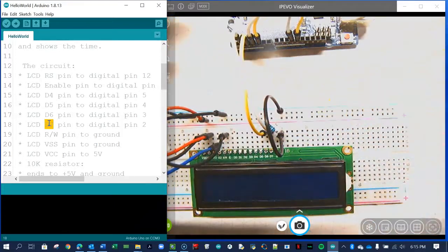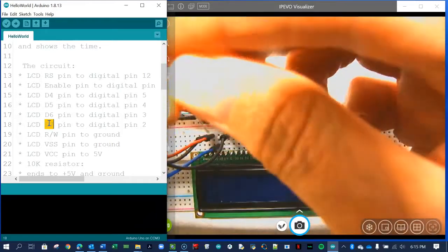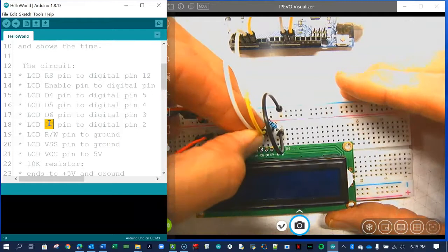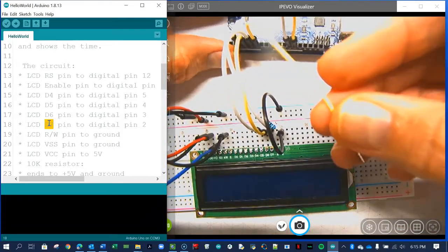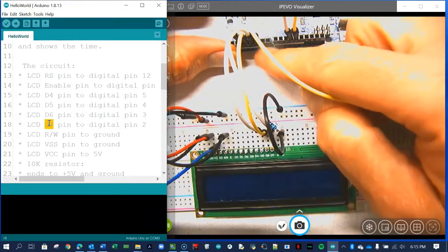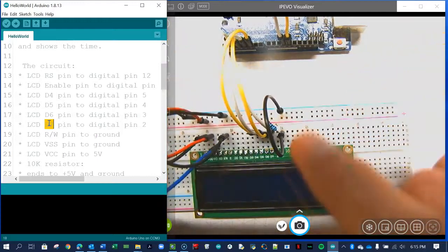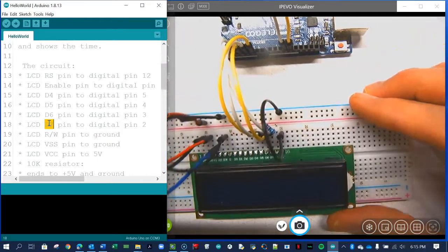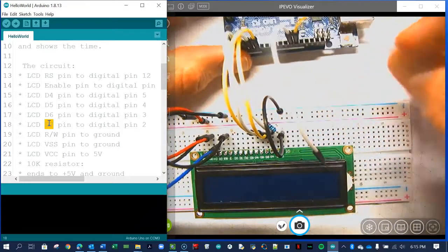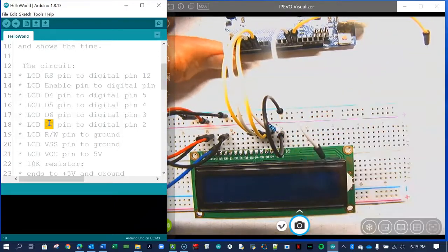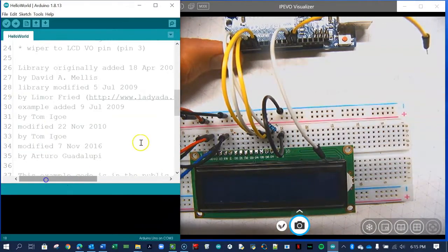The next pin, make sure you grab the next pin, so this should be a white pin, goes into D5. These kind of go in order, they're backwards order. And then pin 5 on the Arduino goes into D4 on the LCD screen. So that looks good. The last 2 pins here are pin 11. You can't really see that here, sorry about that.